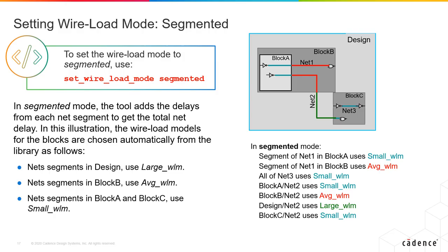This sounds like the most logical choice, but because the tool varies in how it does the optimization, the computation is intensive and it runs very slowly. Also, if there are nets that fall under critical paths, then the wire load model often changes because of the block that encompasses that particular net. Thus the models and the delays that the tool generates for these nets become unreliable.